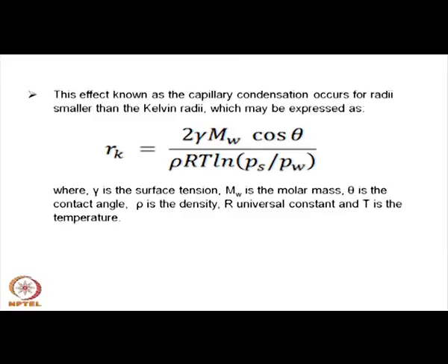In fact, I forgot to mention that the LPG sensors have been used in practice quite extensively based on tin dioxide sensor. So, tin dioxide sensor has been used quite extensively to measure the combustible gases, including the cooking gas. So, gas leakages can be determined by this.